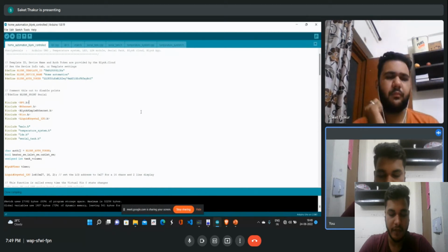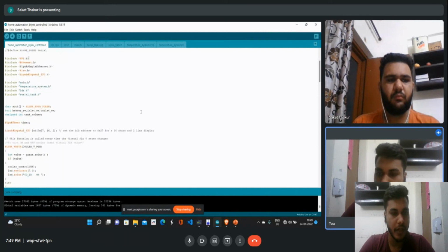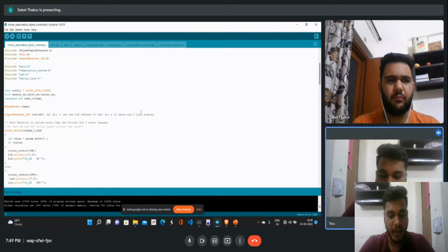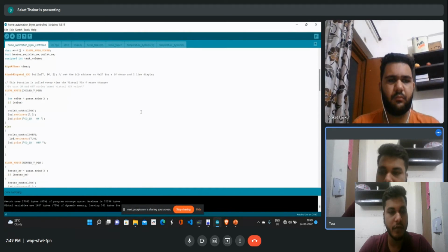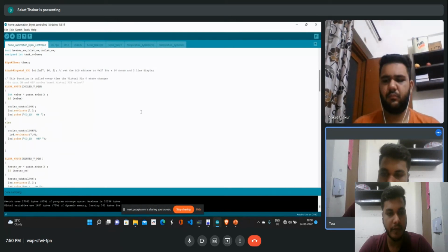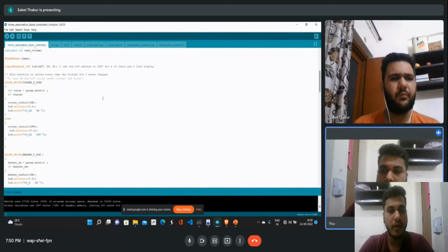Then we stored our private key in a character array. We initialize Boolean variables for input and output that will switch the states of our output, which is simply 0 or 1. Then we set our LCD for 16 characters, and as it is a two-line display, we have to set it accordingly. Turning the cooler on and off is based on the pin value, which is virtually connected to Proteus Lab, which gives us the state, either 0 or 1.